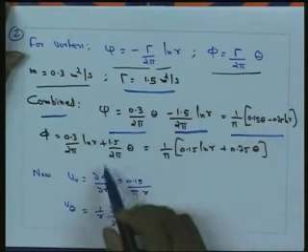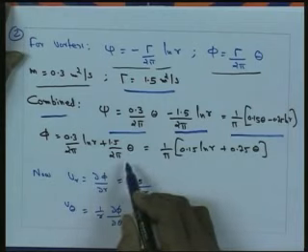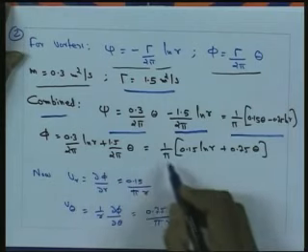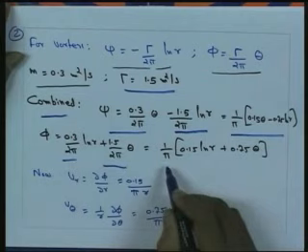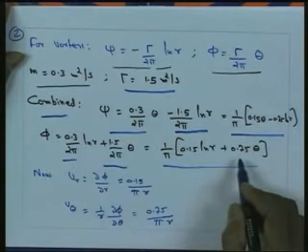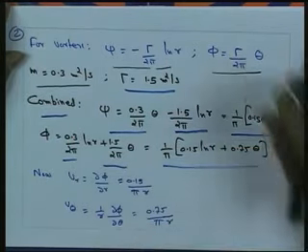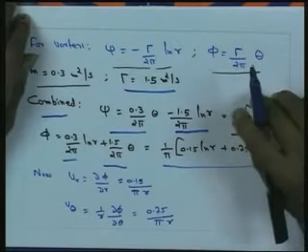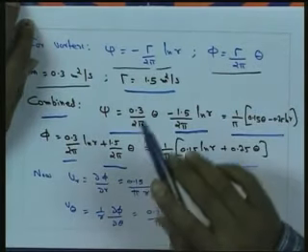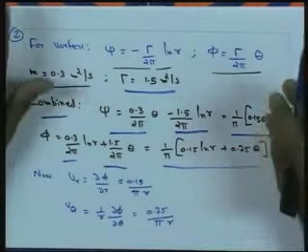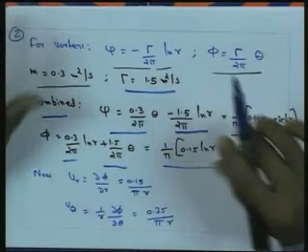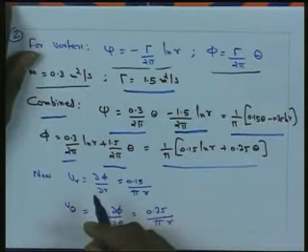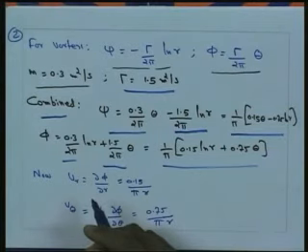So gamma is 1.5, so plus 1.5 by 2 pi theta, so that is equal to 1 by pi into 0.15 natural log r plus 0.75 theta. Thus we get the expression for the stream function and potential function after the superposition of the source and the vortex. Now we want to find the resultant velocity.